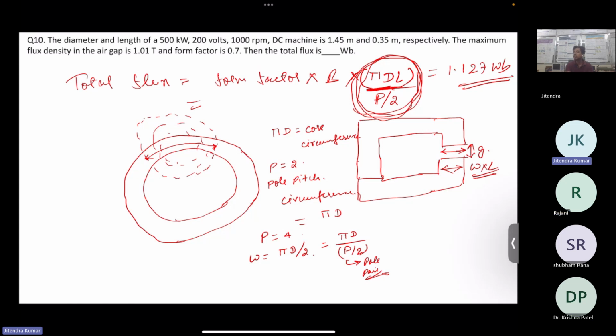Then you see where you can relate with armature drop. The armature drop will be nothing but 5.5, and that value of armature drop can be incorporated in the difference between input voltage and induced EMF, that is back EMF, armature voltage. That is IaRa drop, exactly. So the difference between Eb and Vdc is given for you in the problem, and why is that given? Because the number of conductors are not mentioned in the problem.